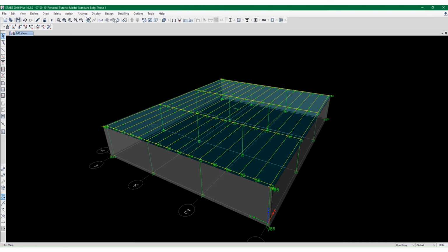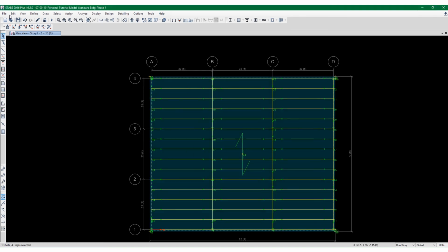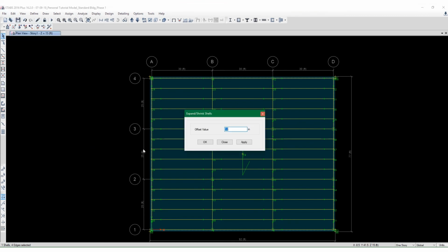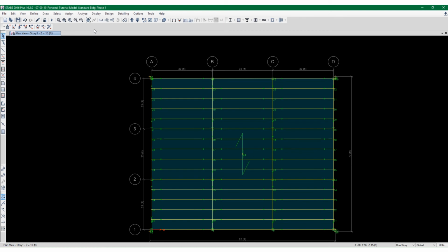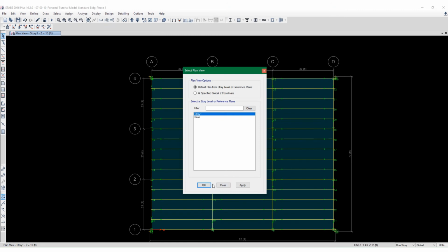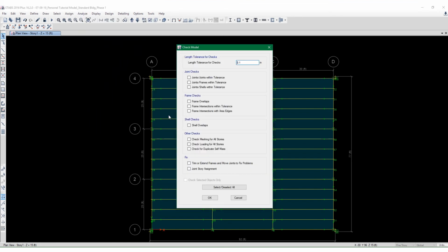All right. So, as I said, the way we solve this problem is to take this deck, bring it back inward 12 inches, and apply it. But you would investigate and see what's going on. So let's say that's the only thing that I did there. I have joints that are not attached to any element at this point. So I'll check my model. We'll see what happens.